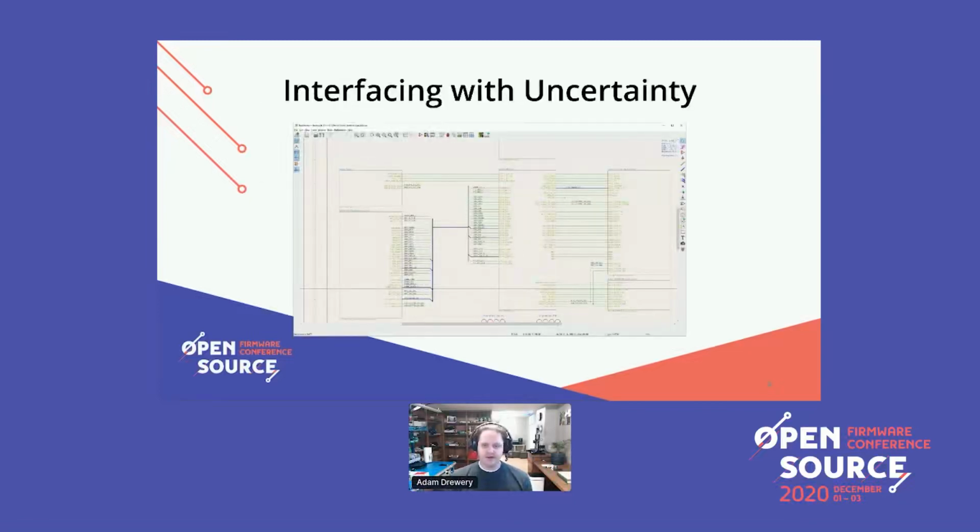So I mentioned that interfaces cause uncertainty. In electronics, connecting two circuits together is really where that comes up. So you have things like loading, or a default pin level of one of them causes the other one to come up in a different mode that you don't necessarily want. There's really a lot of chances to connect things incorrectly.